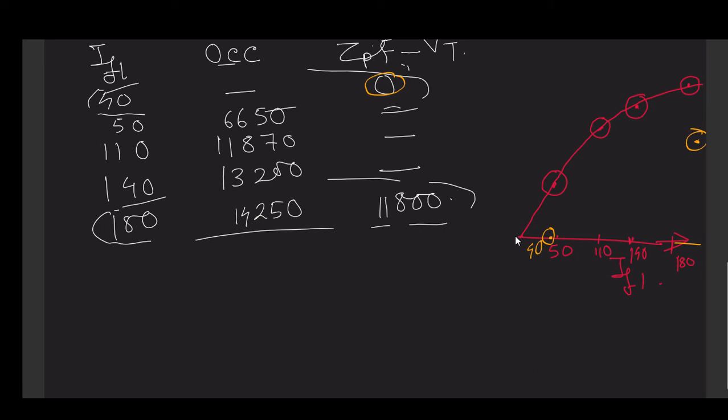So we can say that during that the power factor of the armature current is 0. So short circuit current, how much will be there? Short circuit current will be 78.7. And also that is the IFL.